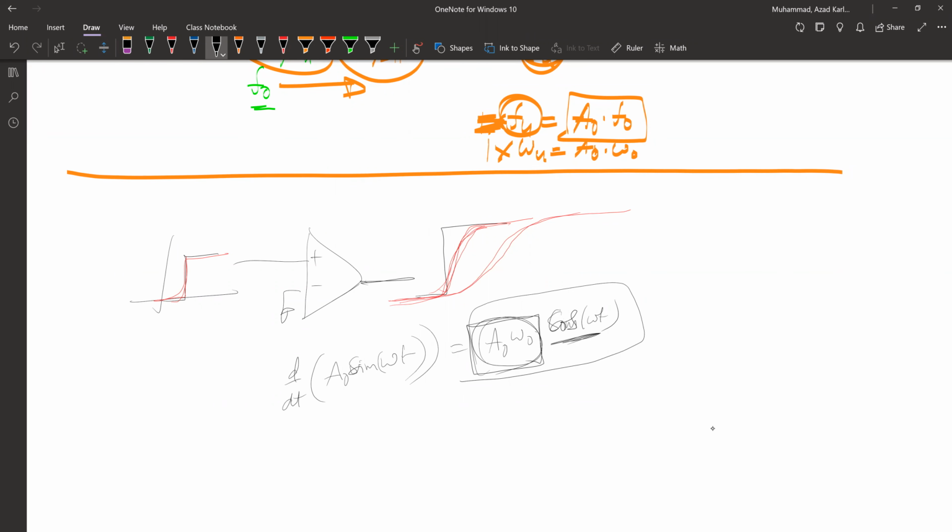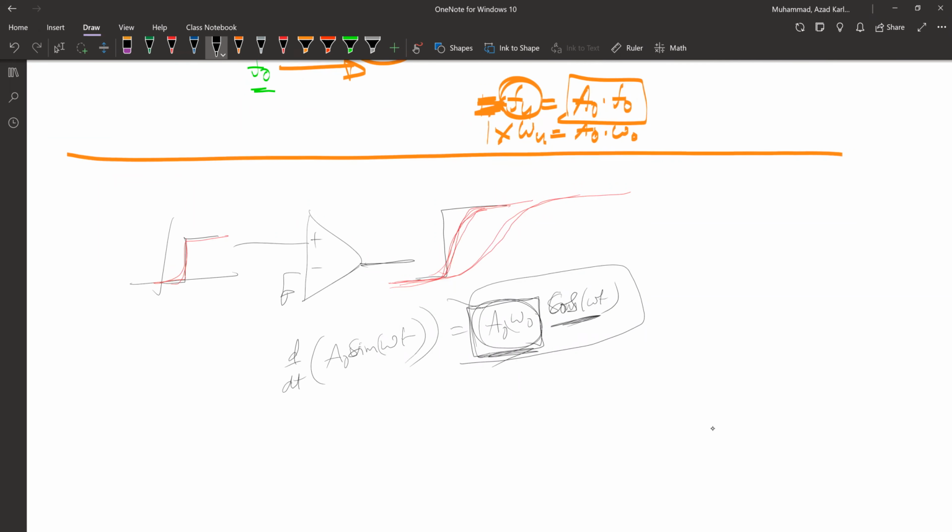So we try to accommodate an op-amp to have at least this much maximum slew rate. It can either accommodate a high change in amplitude all of a sudden, or for a fixed amplitude, a high frequency change. That's what a slew rate accommodates.